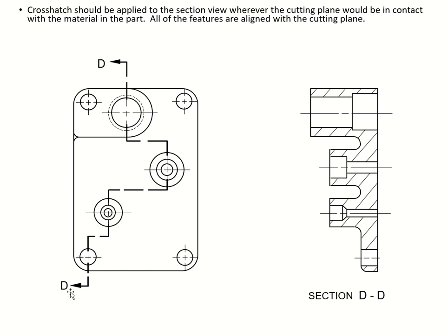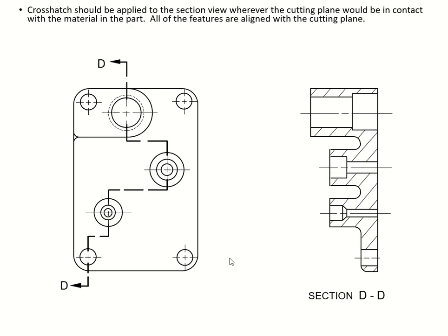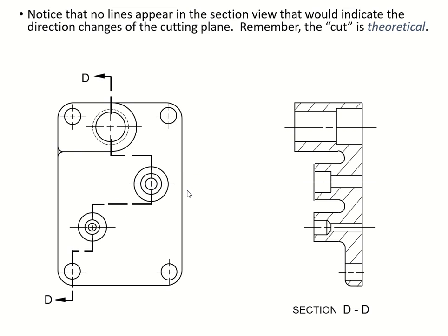And you are on a D-D plane, so therefore your section is labeled section D-D. Pretty easy, okay? So when you carefully look at it, don't forget to put this back. We usually remove the whole thing and then put it back in here, because that's just a theoretical cutting plane. You're doing it actually in your brain.